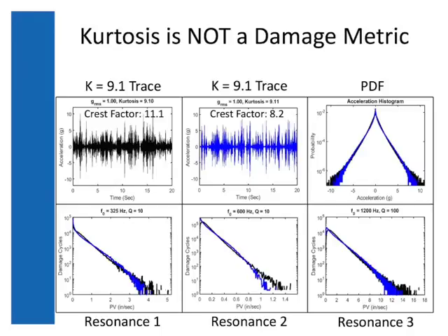The blue trace is taken from the control algorithm that Thermotron just released, Kurtosis 9.1. The black trace is also Kurtosis 9.1, same PSD, fulfills all the same specs. Its crest factor is 36% higher than if you were running on a Thermotron controller. Now that could very well be field data if you somehow generated a spec from the field. Frankly, that could be somebody else's controller, because we've tried to a limited degree to match our damage to what we see in papers written by other manufacturers, but that's an inexact science at best.